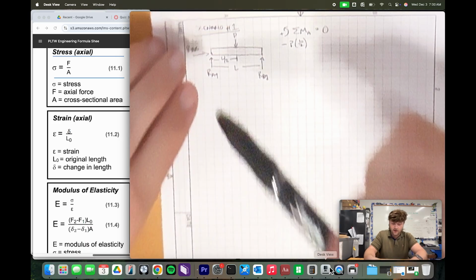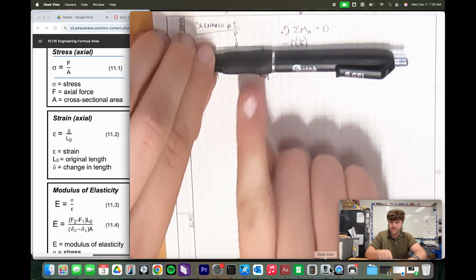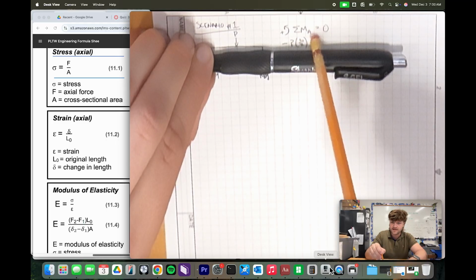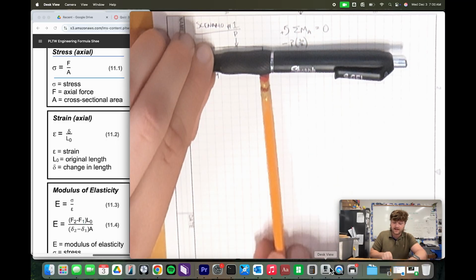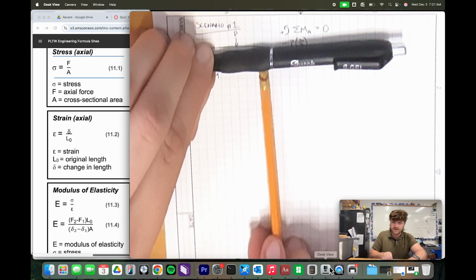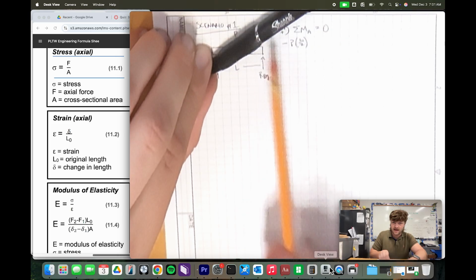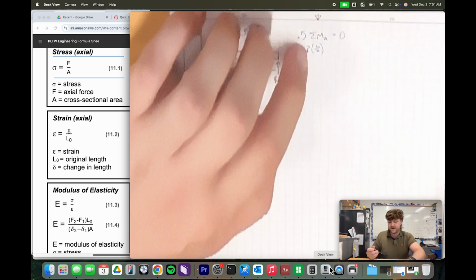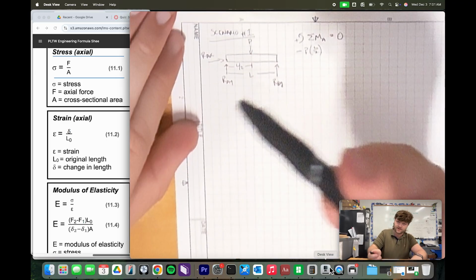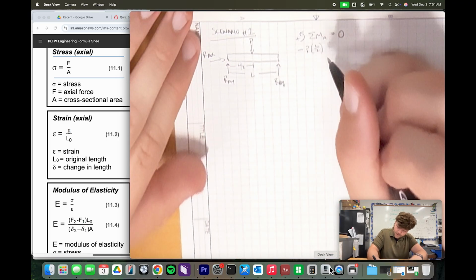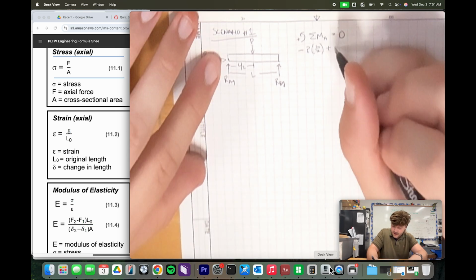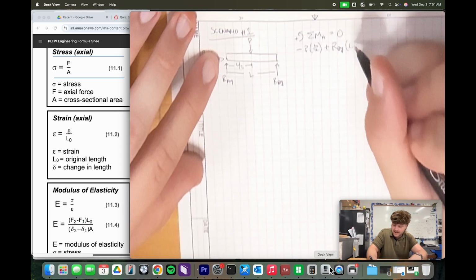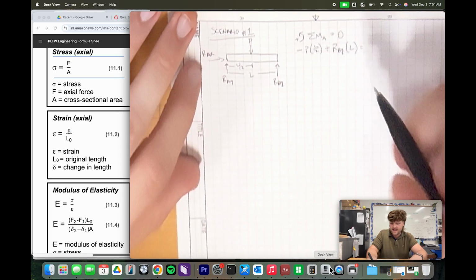And now, if we also have the beam hinged about point A, because we're calculating the moment about A, and I apply this reaction force B, as we can see, that is going to be counterclockwise rotation, how our pin's moving. So it's going up this way, right? That's following this direction in terms of curvature or rotation, so that's going to be positive. And then we can take RBY times the total length of the beam, and that's going to be equal to 0.